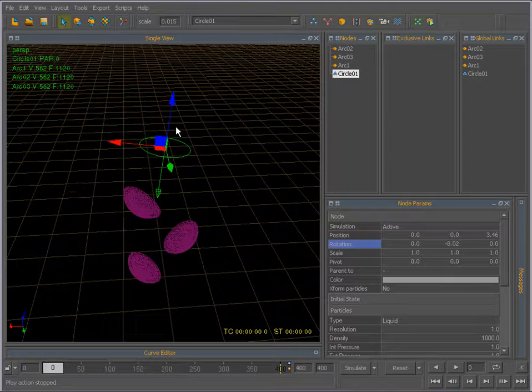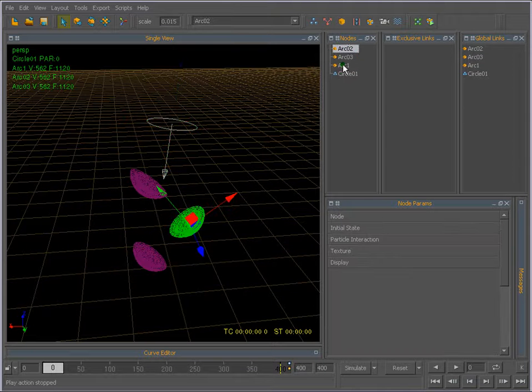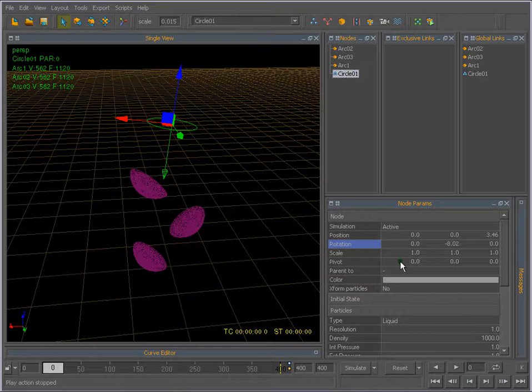Now, as you can see, the circle emitter is a bit too big for our objects here, so we need to turn down the size. Make sure that when your circle is selected, it will highlight all the panels here. You can select the rest of the objects from here. So now it's circle selected, so we come down to scale and we need to change the scale here to 0.3, 0.3, and 0.3. Right, so it's now small, it looks like a hose now.